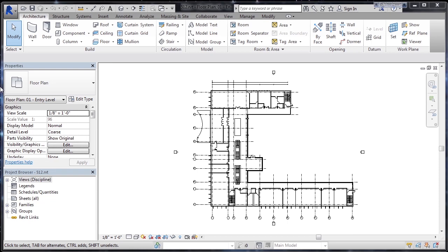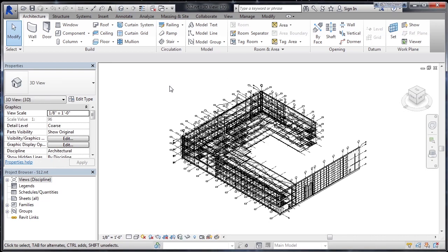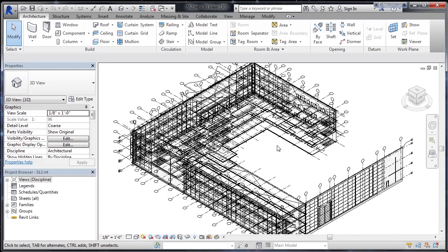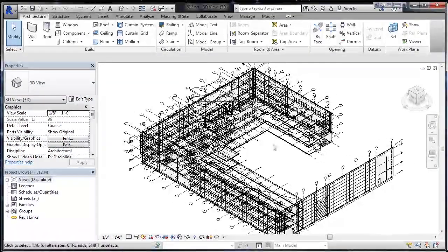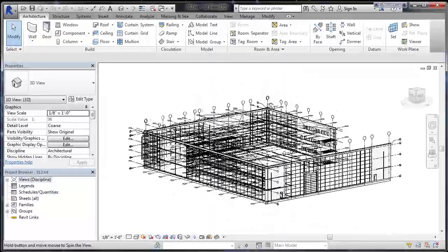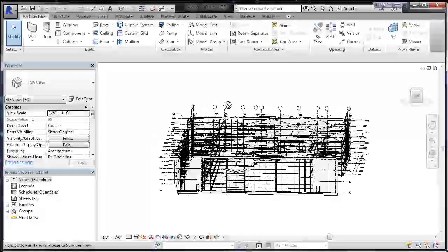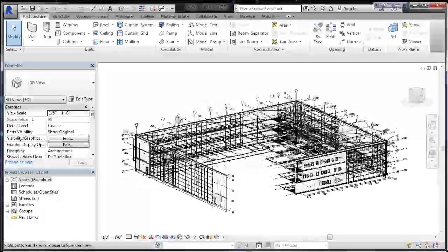But if you change your view to the 3D view, just by clicking the house on the very top of the Revit screen, what you'll notice is this 3D model is made up of several 2D flat CAD floor plans and elevation plans. So if I zoom in, I can actually see the floor plates here are just 2D flat files, and the elevations are 2D flat files.